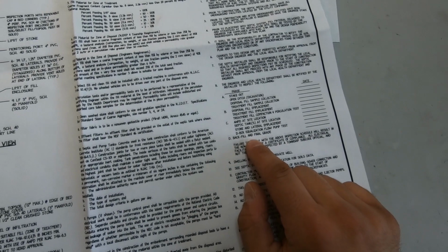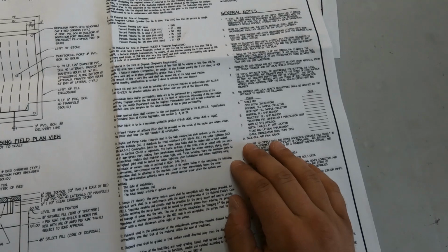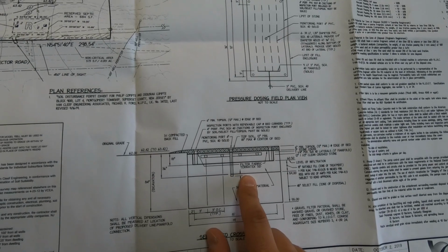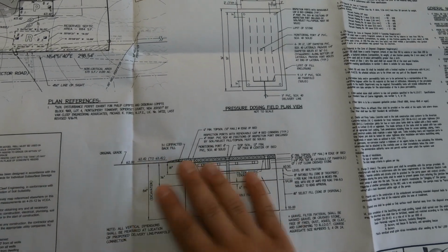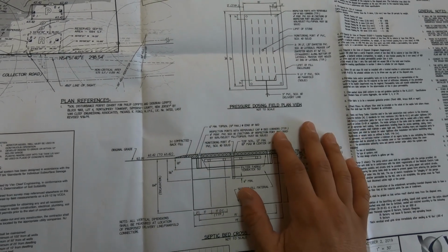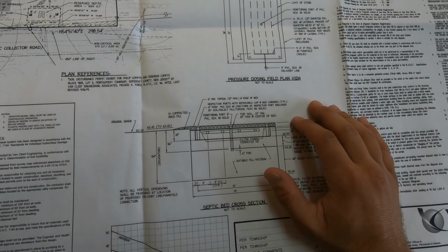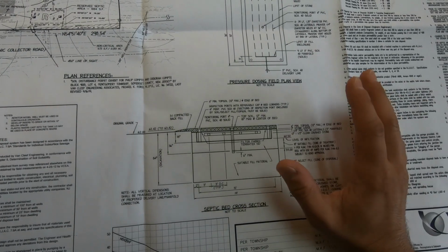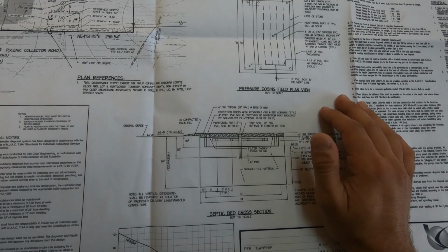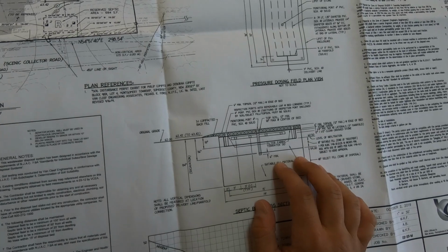And then the last thing that we're looking for is the backfill and the final grade. So once the system's complete, once you've done the pump test, they'll cover everything up. You've got your topsoil layer here. It's shown in the cross section, and a lot of the time they'll seed it and put hay on top of it so that the grass regrows. Sometimes it's the contractor that does it. Sometimes it's the homeowner, but that's usually what happens. And then we come back at that point, take pictures, make sure that the slopes look all correct, and they didn't leave the site area a mess. And at that point, a lot of the time we'll do our as-built tape measures.